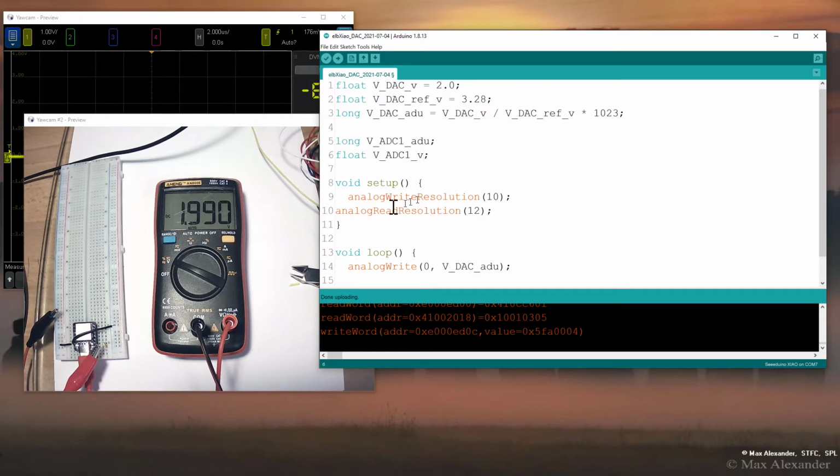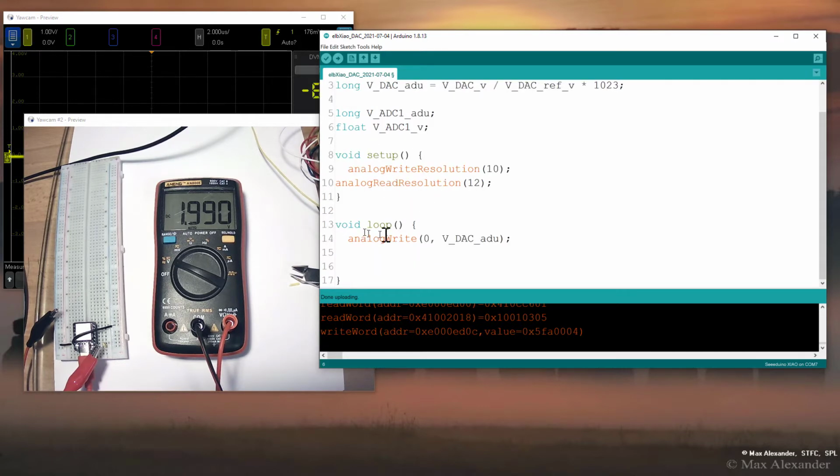So I've got my variables, and now we're going to read a value from the ADC. That's going to be an analog read. Oops, it helps when you spell it correctly. Analog read, from channel 1, and that's it. That command says, okay, go read that value and return it.